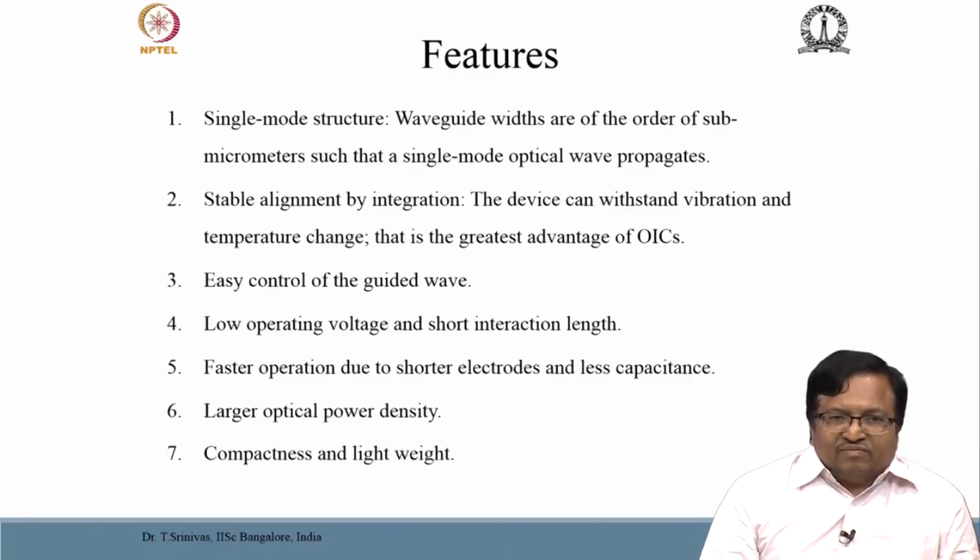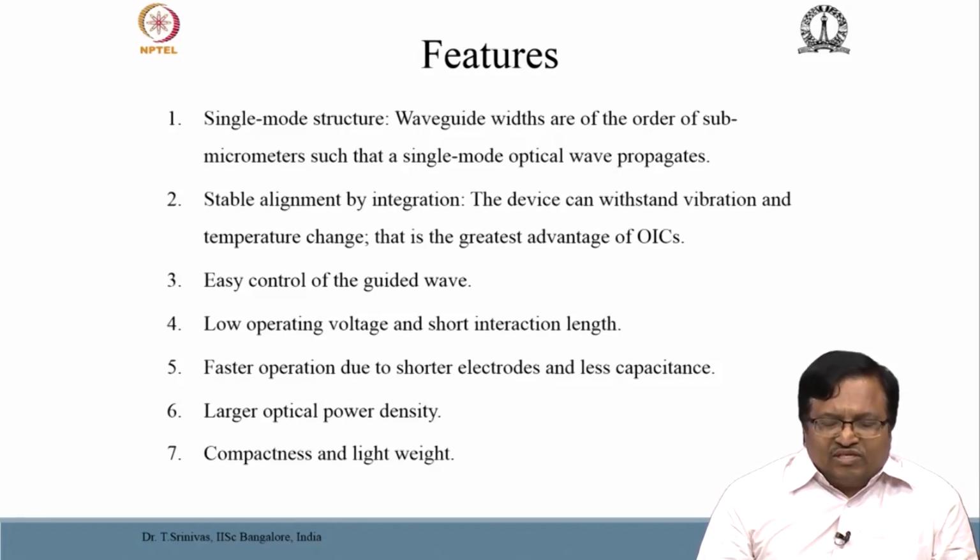The power density of light propagating in these waveguides is very large. So, you can expect many nonlinear effects which can be used effectively in photonic integrated circuits. Of course, like in VLSI circuits, these are very small. So, they are very compact and lightweight, they consume less power, and batch production can be used to fabricate devices and so on. These are the generic advantages of going for miniaturization and batch production in photonic integrated circuits.